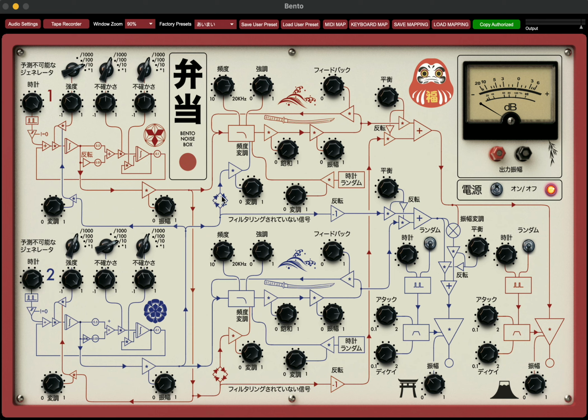As you can see, the signal of the modulation of the cutoff is rectified, so we have only a positive waveform to modulate the filter. This is done to avoid negative filter frequencies. And let's see what happens now.